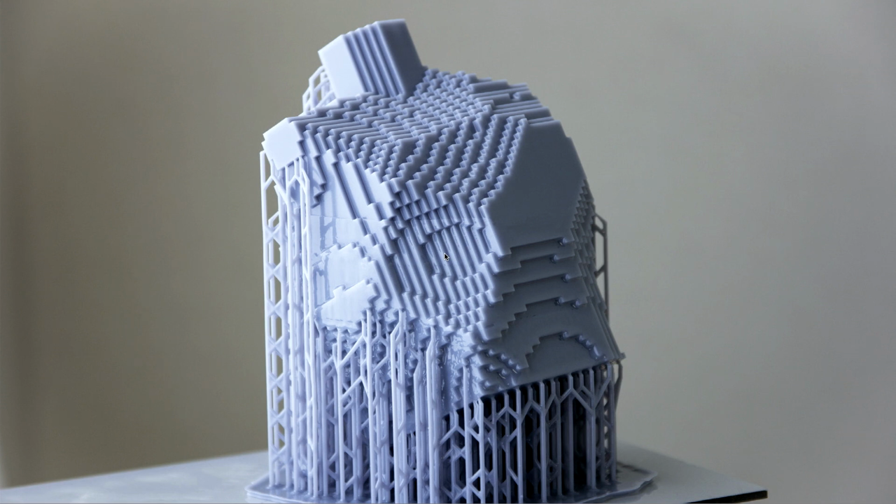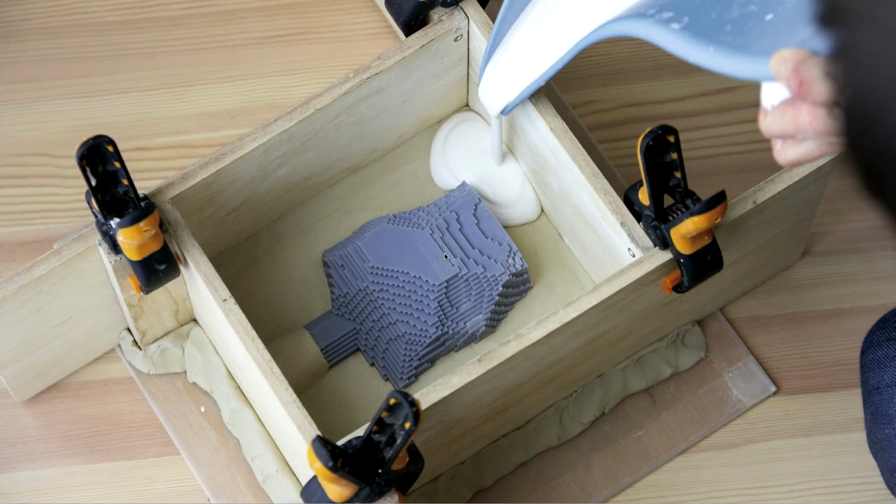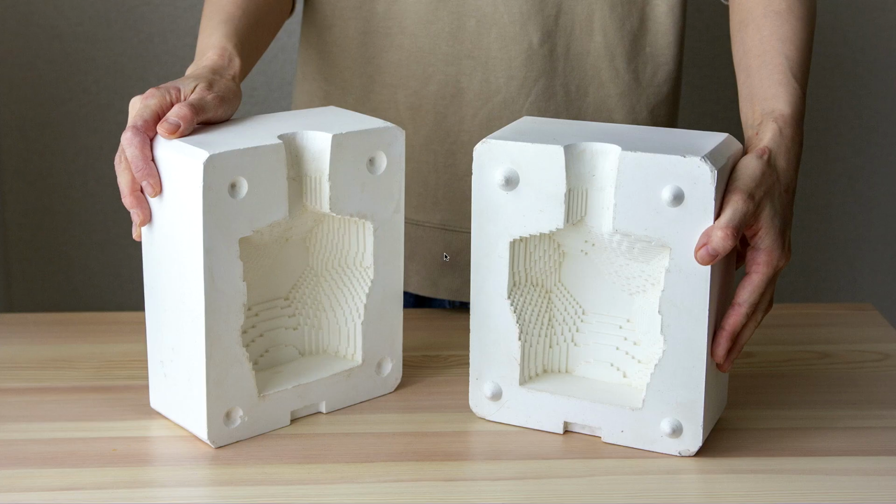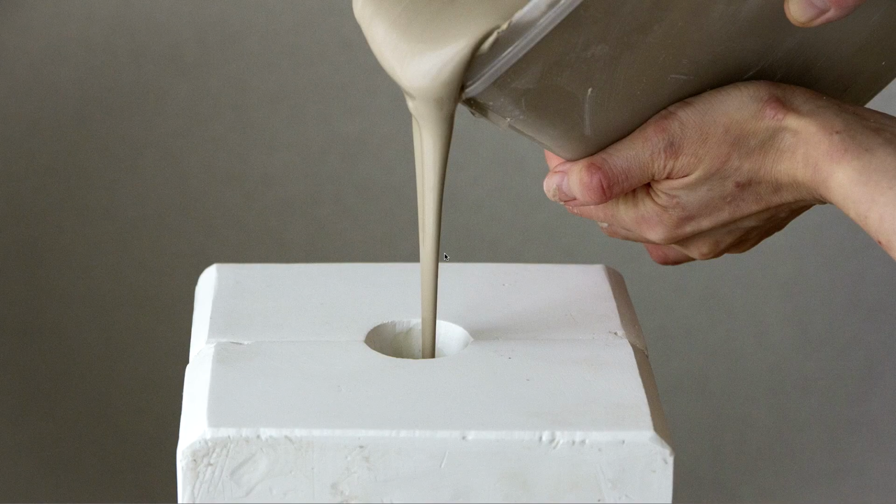So the next step involved creating the physical mold and casting the object. First, we finalized the geometry and 3D printed it using an SLA printer. In this case, we're just using the normal resin material, which provided a high level of precision. Then we put the 3D printed objects on a vase like this one and poured melted plaster over it to create a mold. Once the plaster hardened, it becomes a reusable mold for casting like this.